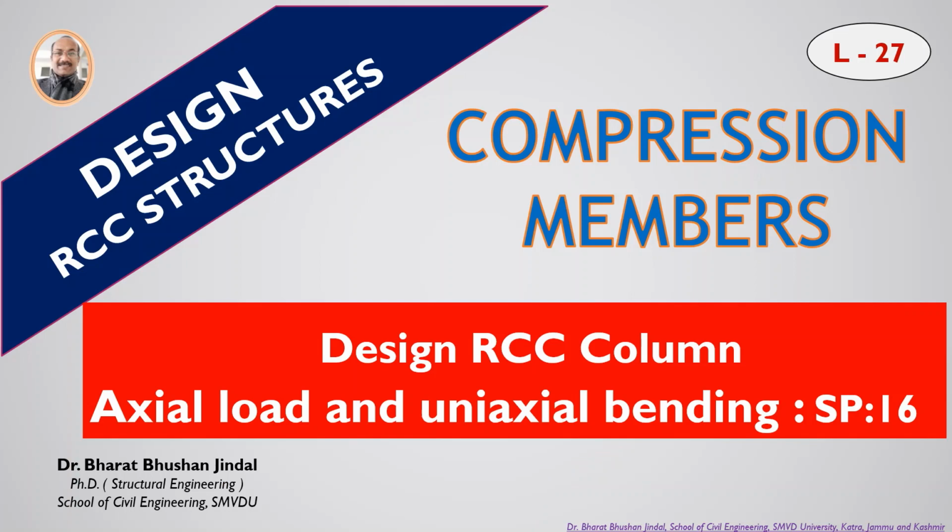Welcome to all of you in today's lecture number 27 in this series on compression member design. Today we are going to discuss the various conditions, the various IS 456 guidelines or design parameters which we have to take into account while designing an RCC column, that is, an RCC short column having axial load as well as uni-axial bending.